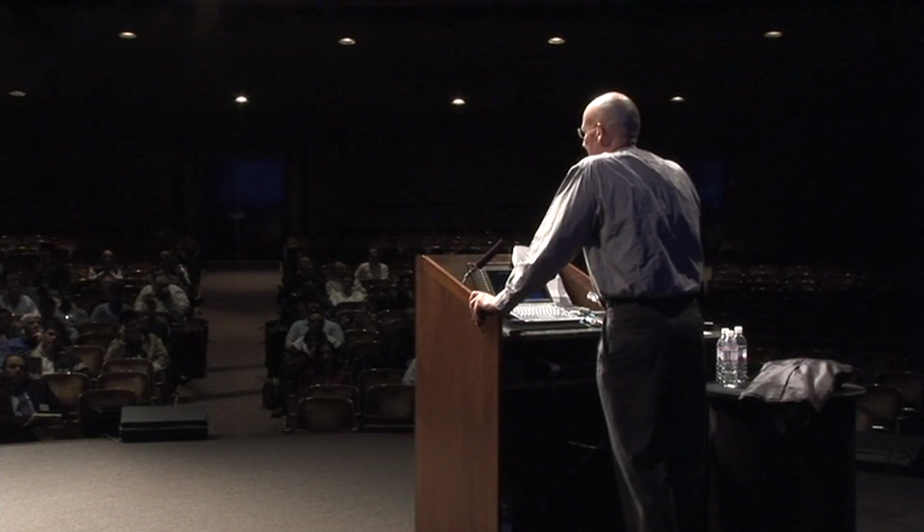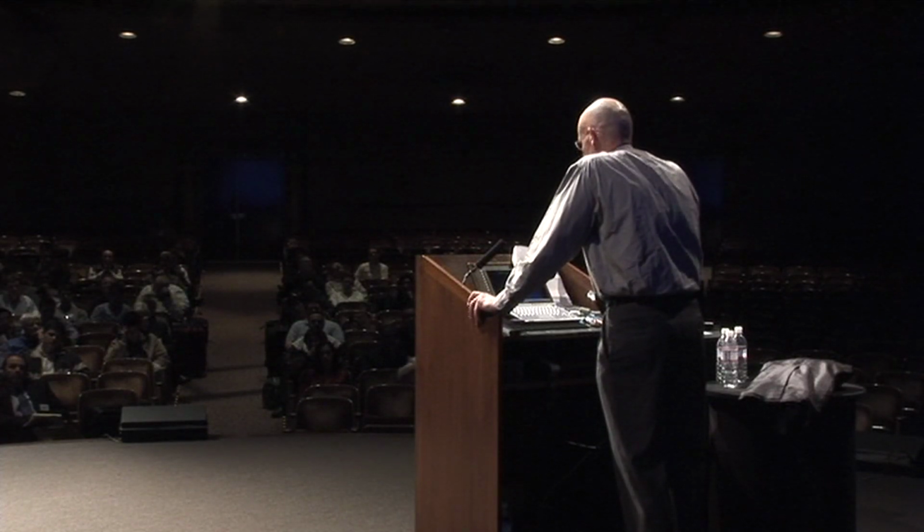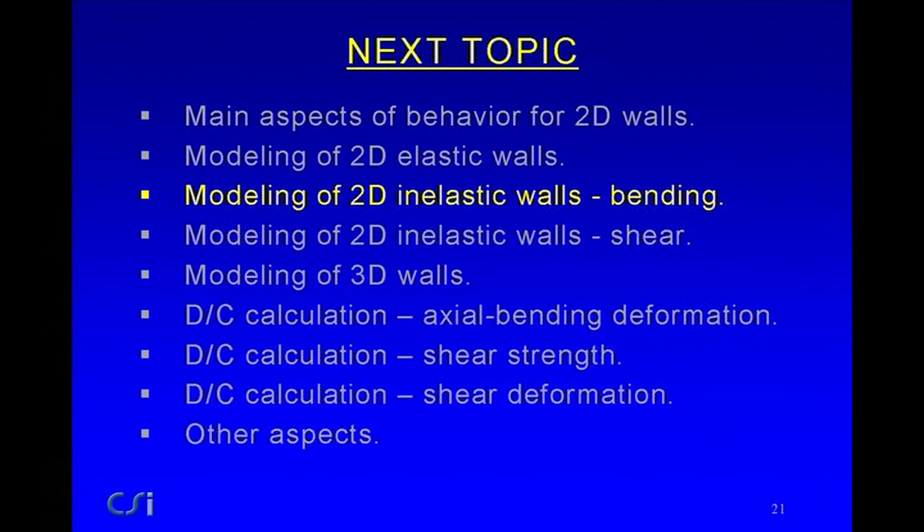And that really is a key point. If you're using true strength-based design, an elastic analysis of this type is nowhere near accurate, but it's plenty good enough for getting force demands and force capacities, but force demands primarily. If you're doing an inelastic analysis, that is really no longer the case, that a mesh like this may actually be counterproductive. And I'll be talking a little bit more about this.